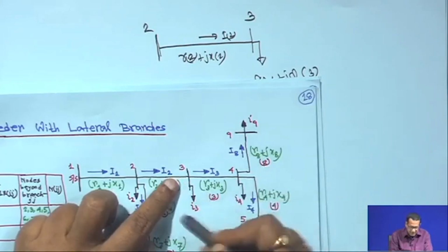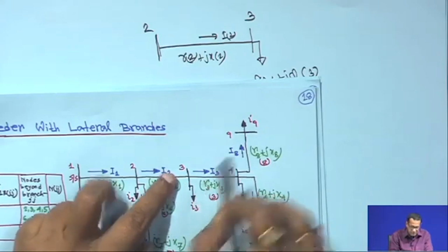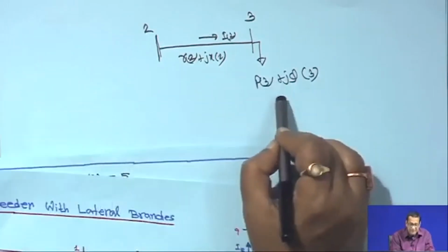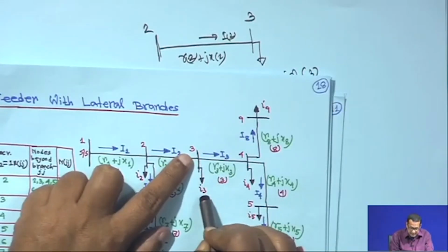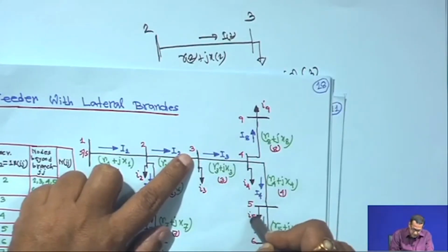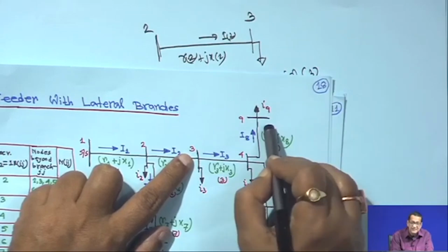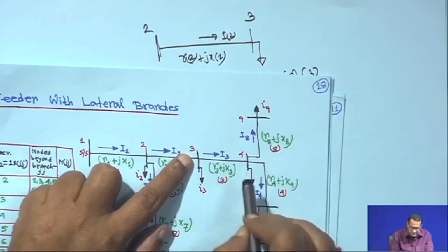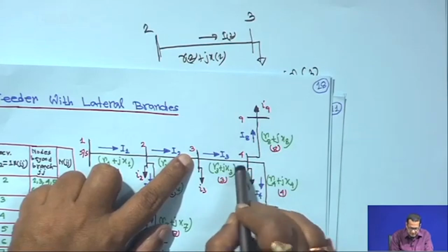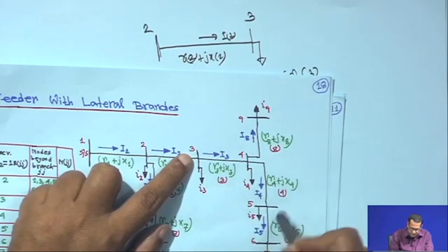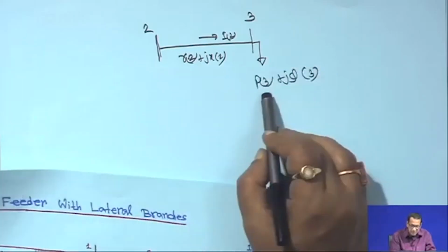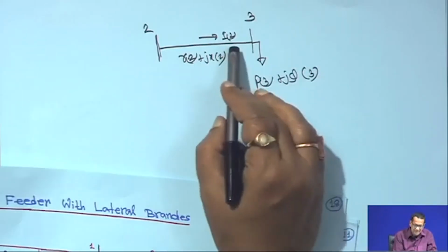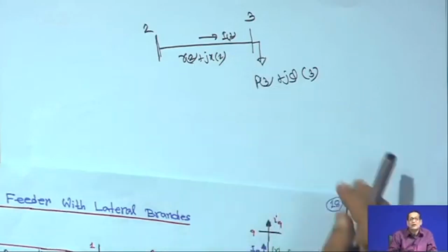Similarly, for the reactive load, the total load fed through node 3, Q3, should be the load of this node itself, QL3 plus QL4, QL5 and QL6 plus QL9, plus the reactive loss of branch 3, branch 4, branch 5 and branch 8. That is the total P3 and Q3, and that is the meaning of electrical equivalent.